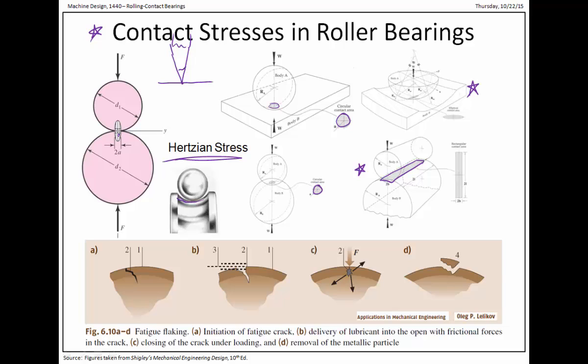Where there's a compressive stress that gets distributed, my understanding, or what I've heard before, was that there's a very peak stress that will happen because of this. If you were to take maybe the von Mises of this condition, you would find that it would be just underneath the surface. And the result of that, when highly loaded, is that a little chunk can get spit out because of where that high stress is located. And the result of that is a pit, which is one of the common things in the failing of contact